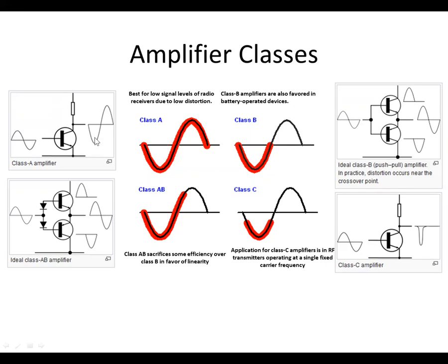Receivers do low distortion because the transistor doesn't have any trouble going through the zero cross point, because it's biased. Say if it's a 10-volt power supply, you would typically want to bias the transistor with the biasing resistors to hold this at, say, plus 5 volts. So it may go then from 5 volts down to close to 0, and then back up to 10 is the operating range. So there's no problem crossing over what is the signal's zero level.